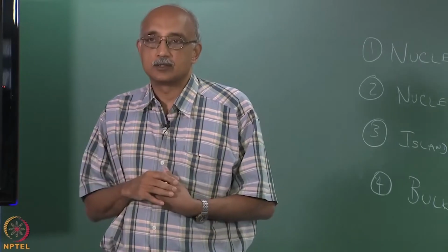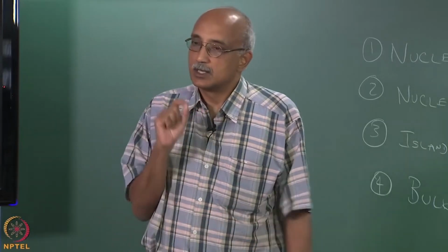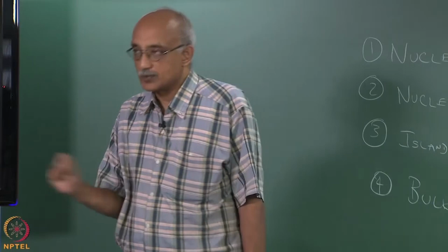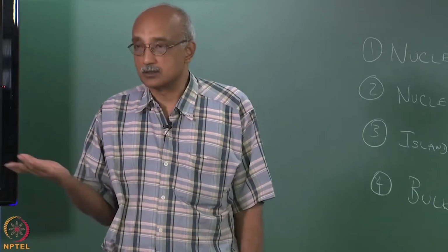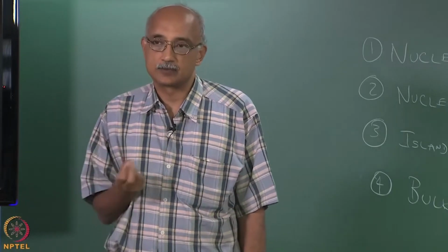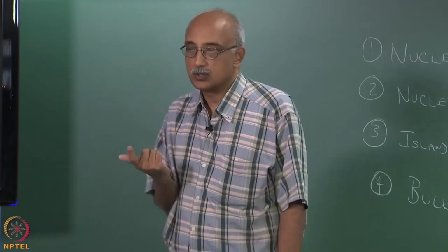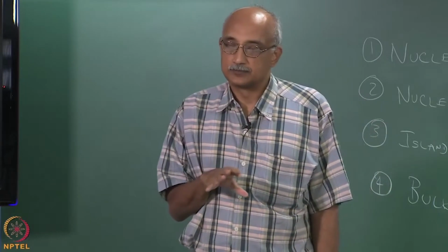N2 is relatively inert, so usually does not bother us, but oxygen, if it seeps in, can certainly affect the composition of your deposit. Another one is water. It is very difficult to keep moisture out of CVD chambers. So, oxygen and H2O are frequently contaminants that will enter your CVD system.